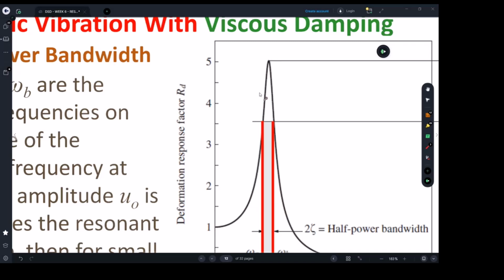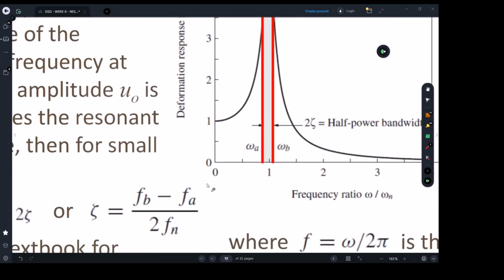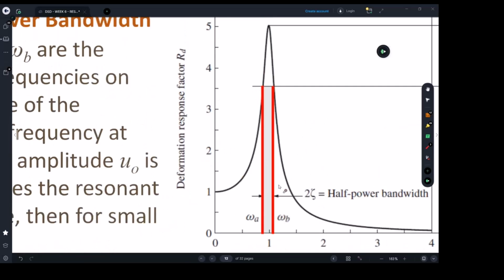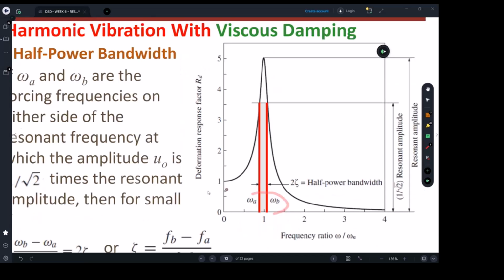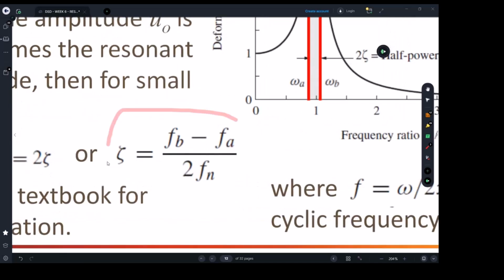You're going to go to the site and apply some harmonic motion, and you will be able to plot the frequency curve. Now, sometimes we need to find particular parameters, like maybe the natural frequency or maybe the damping, whichever you don't have. So you can work in whatever direction, and by determining this level, you will be able, by the graph, to determine these two lines, eventually these two omegas, and then work out whichever unknown you want.